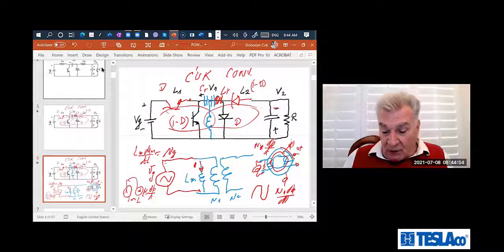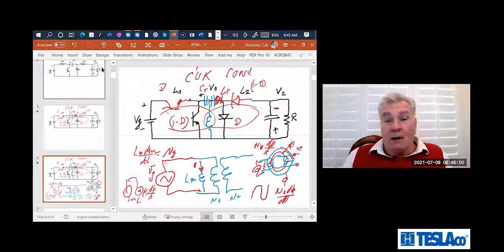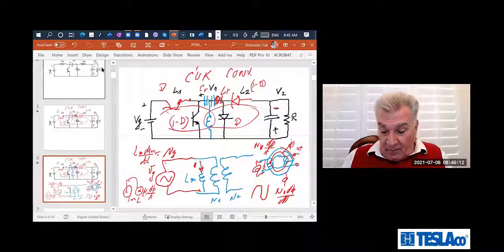Then what happens? In this open load, all you're seeing is a small current on the primary. So a 60 Hertz transformer operates in such a way at night, when nobody is using electricity. That's what happens, and you have this so-called magnetizing current.